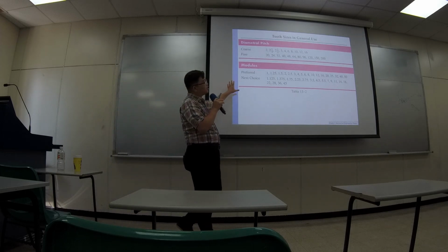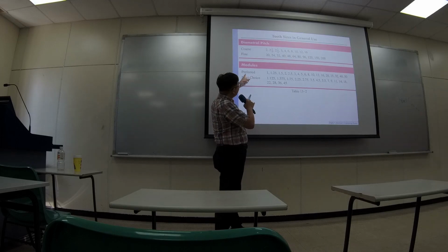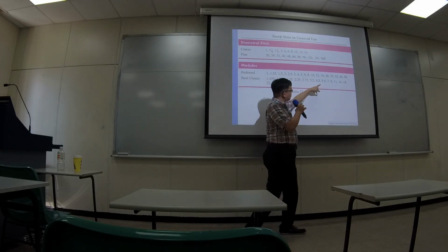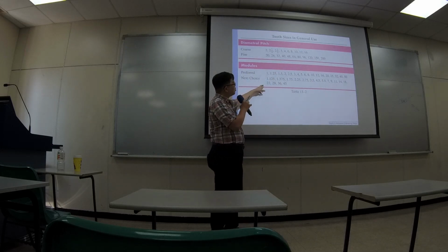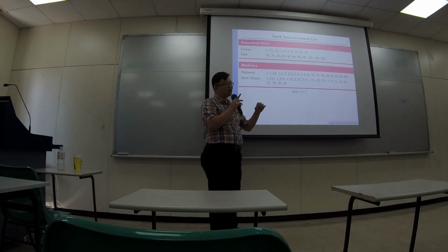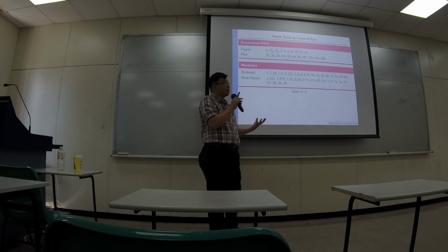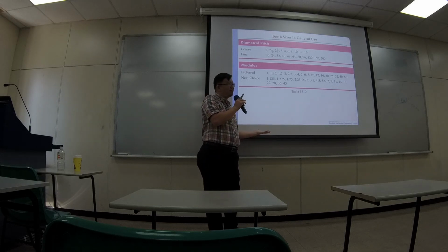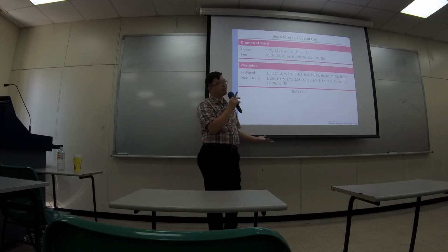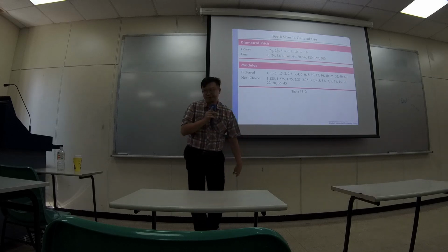They usually give certain numbers to those values, like these. Like this book is supported by one manufacturer. They only prefer to have certain numbers of modules. They don't want you to design gears in different numbers of module, because usually you cannot buy them. You don't see them in the market. If you don't have them, maybe you can only manufacture by yourself or 3D print by yourself, and the quality may not be good enough. Okay.